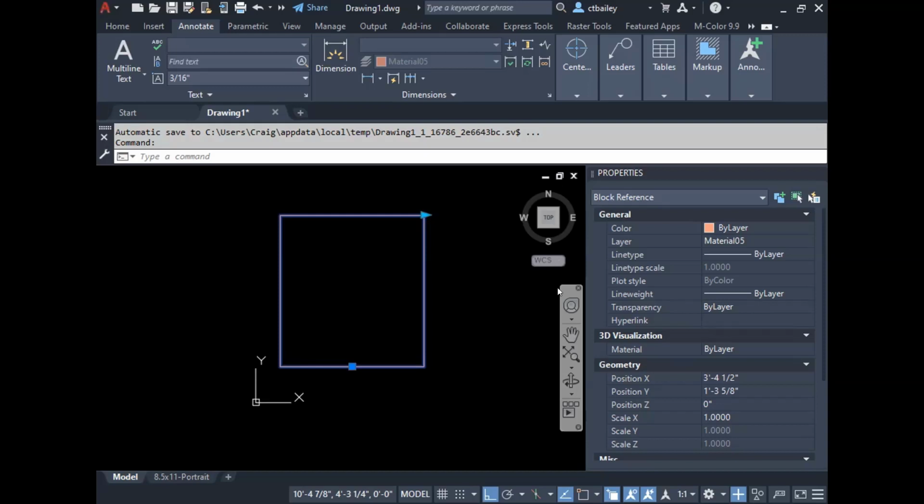What I want you to do is select everything, start the move command, the regular AutoCAD move command. Select everything. Midpoint of the bottom line. Shift right click, midpoint. Choose midpoint, bottom line. Click. Now type 0,0,0. There you go. Okay, now you've set it up in the proper place for the basement.